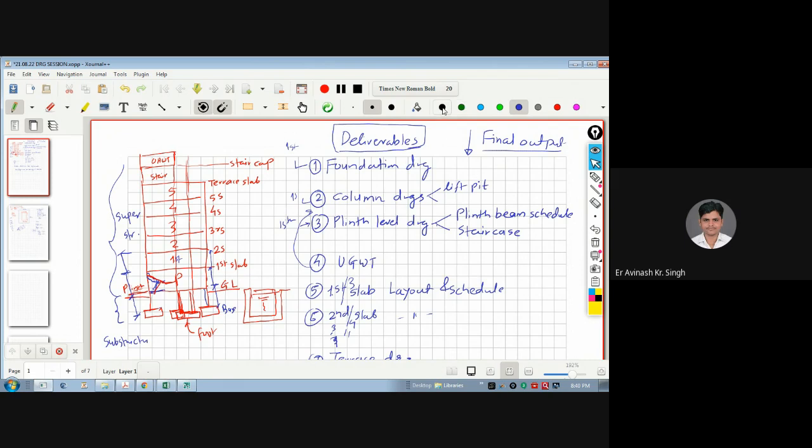Cleaning the site. Foundation. Okay, we will do the excavation. I just want to go regarding RCC. So we will do the excavation, do the PCC first. Once you do the PCC, we will cast the footing. And in the casting, we will also have a column, don't forget. Then once you cast the footing, you will cast the column till this portion. Then you will cast the beams, plinth beams.